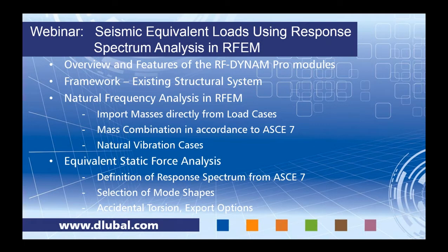We'll be performing a natural frequency analysis today in RFEM. Here we'll be importing masses directly from load cases. We'll create a mass combination in accordance to the ASCE7, and then we'll be taking a look at the different natural vibration cases. After this natural frequency analysis, we'll go ahead and perform an equivalent static force analysis.